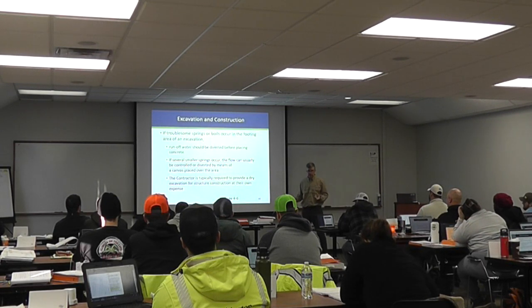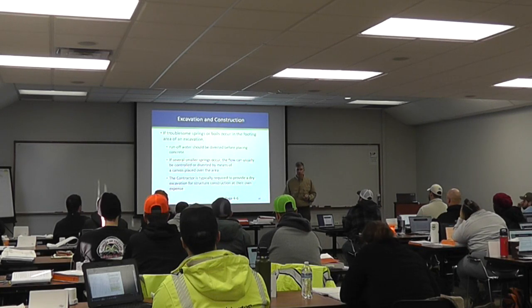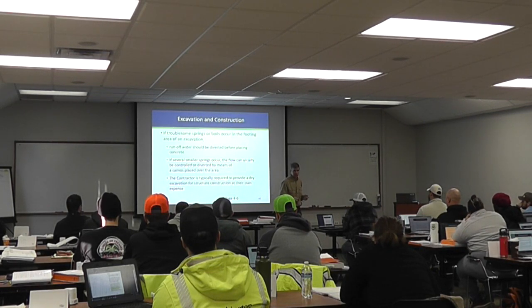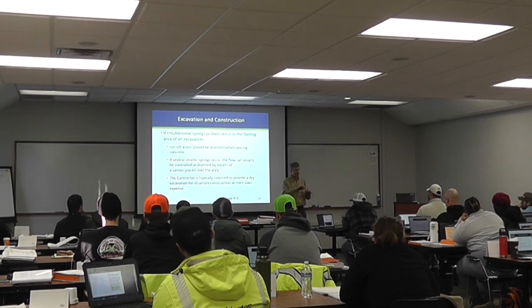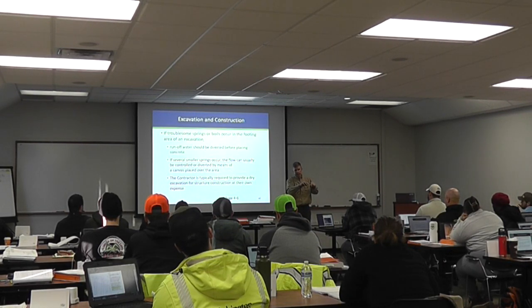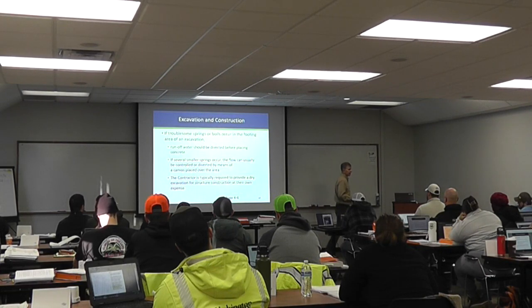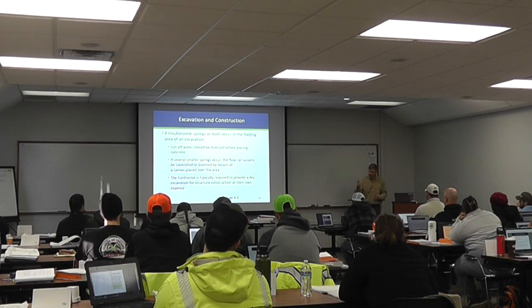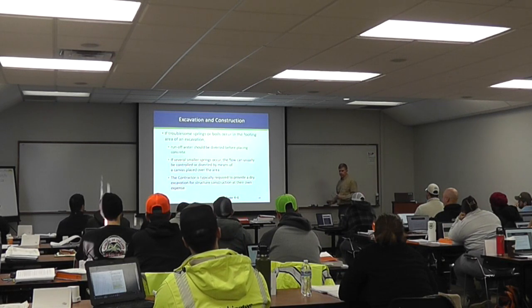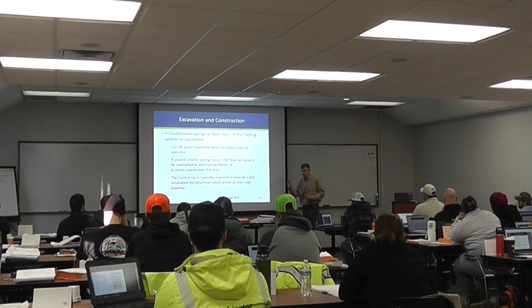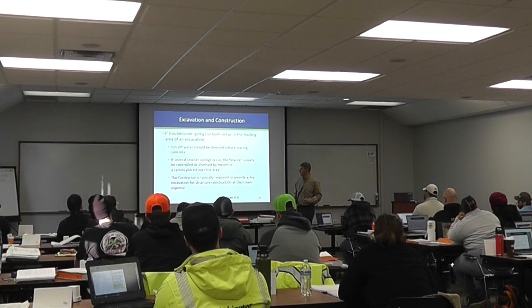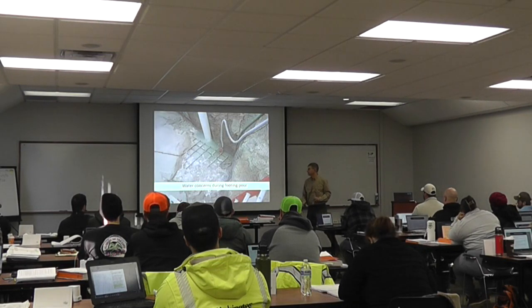So we had a kind of a major artesian coming up on one of our piers on St. Croix. And they ended up using what they call French drains, which essentially is like a half pipe of PVC, and then a little trench, and the water would literally flow out the trench to the corner of the footing and then pump it out. But the thing was coming pretty good, and everything worked out pretty well. We saw a couple little pieces of water, little trickles of water that came up, but we were able to keep it pretty decent.